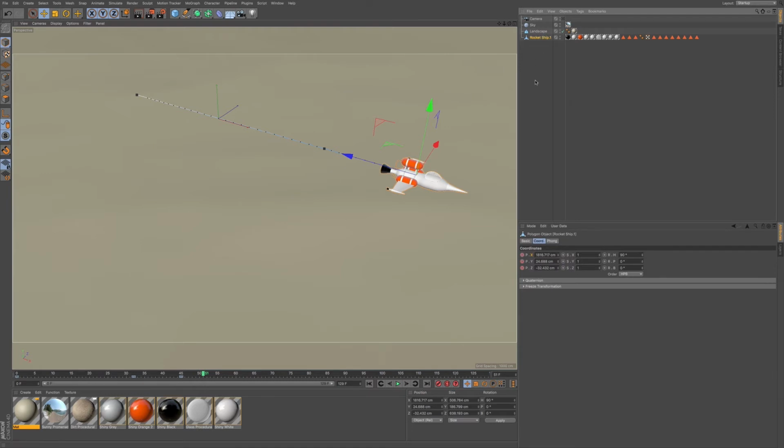If I click on the object, these red circles are now on when all you're doing is just moving that one object along the X. So let me show you. We're just moving along the X. You can see this value changing, but we still have these keyframes here. So I just want you to be aware of what happens when you're using auto key.